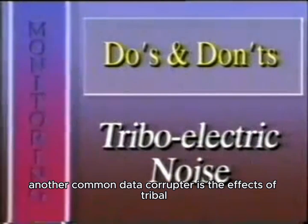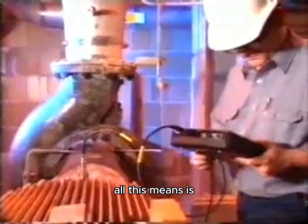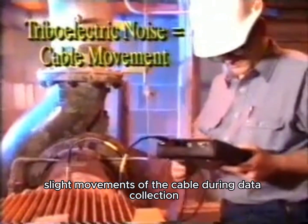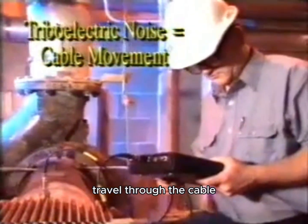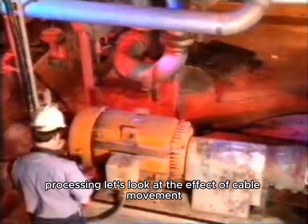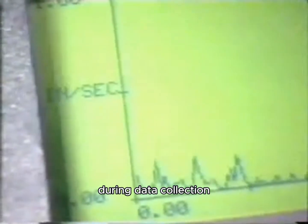Another common data corrupter is the effects of triboelectric noise. All this means is slight movements of the cable during data collection produce changes in the way signals travel through the cable, and these changes are magnified by the signal processing. Let's look at the effect of cable movement during data collection.